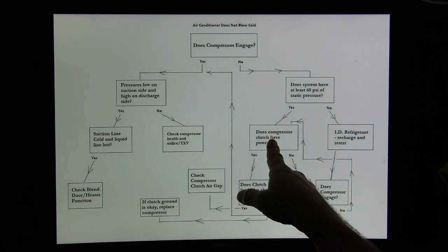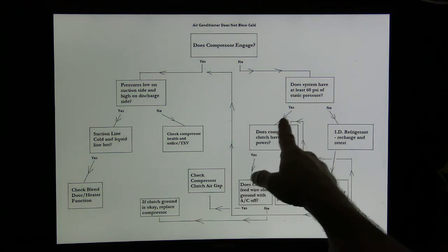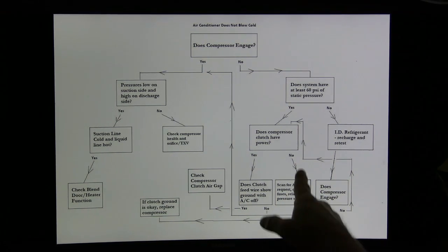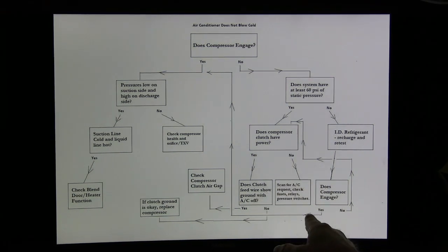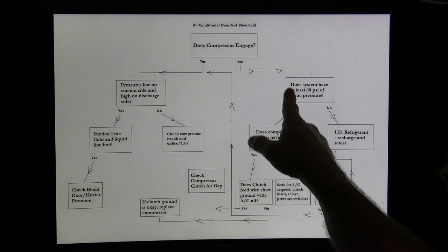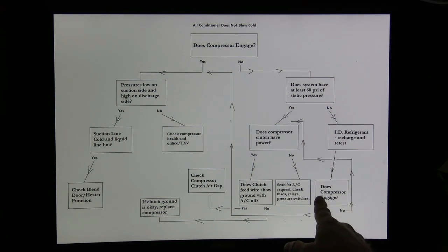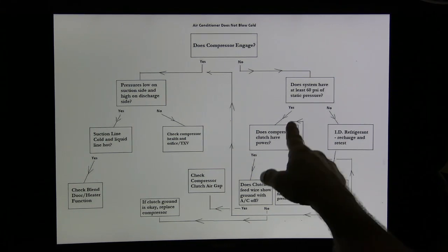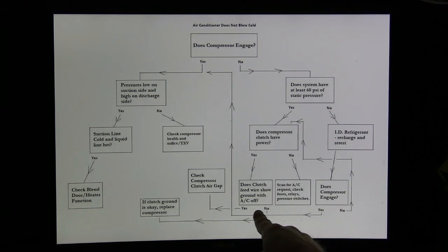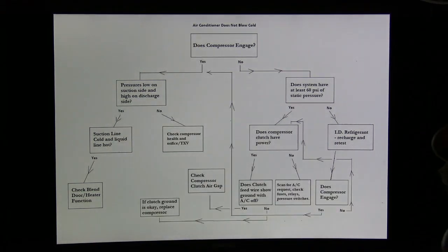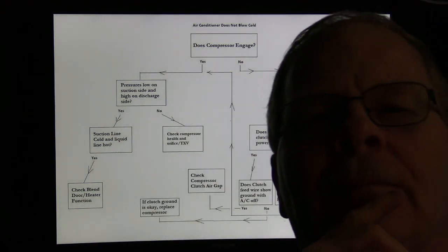If the compressor clutch, does it have power? If it doesn't have power, you're going to scan for AC request, check fuses, relays, and all that kind of stuff. Alright, so does it have 60 psi? If not, I need the refrigerant recharge and test. If the compressor doesn't engage, you're going to go back here. If it does engage, you're going to go here and then come back over here, and so on and so forth. That's a pretty neat little chart, and it works most of the time.